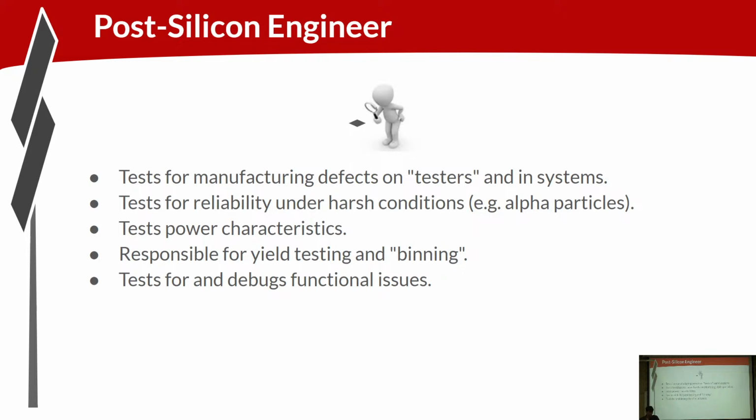They'll also test the power characteristics of the model. One of my brief roles was coming up with the power virus for one of the chips that we created. So the power virus is the test that will be run to stress the power as much as possible on the chip. So every chip that comes out of the factory is going to go through a standard litany of testing. The power virus is part of that.